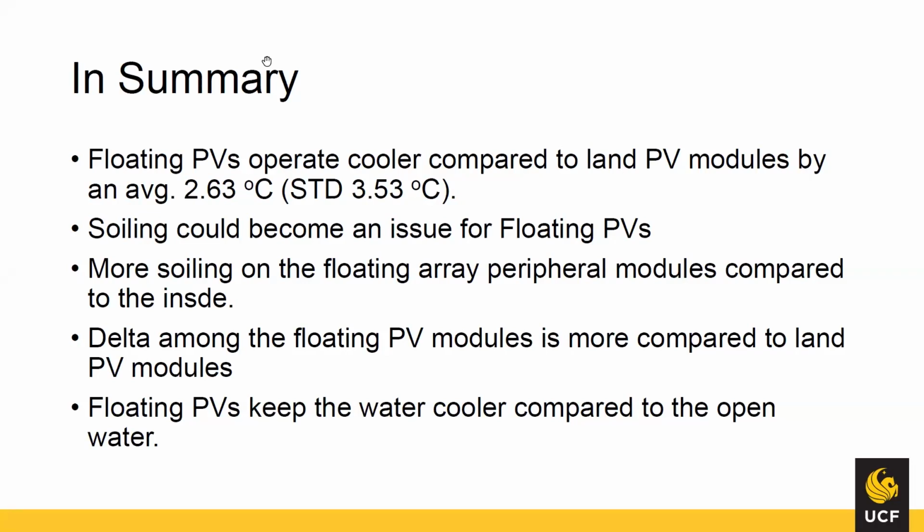Very true, and we did use the temperature coefficients for the models. So the CEC model that we use, the SAM model, we take the actual module model and throw that into the model. We take the irradiance, the module temperature. Based on that model, we had 5 locations, 3 points per location.